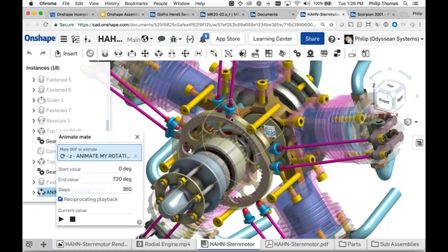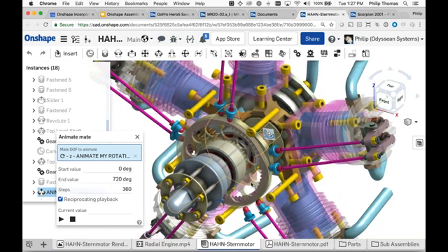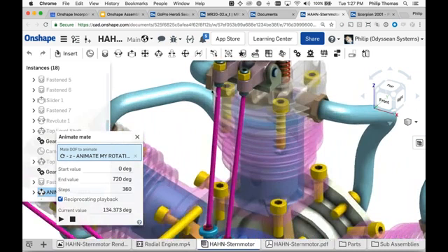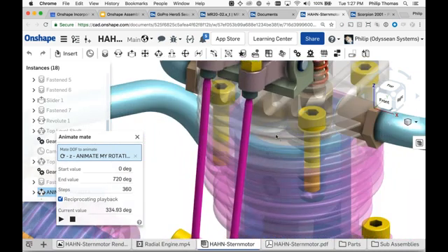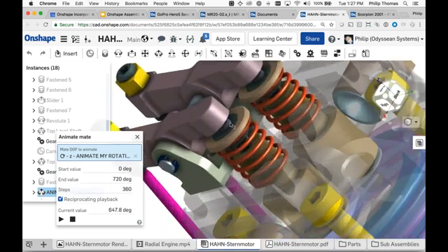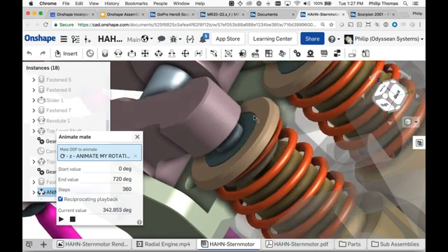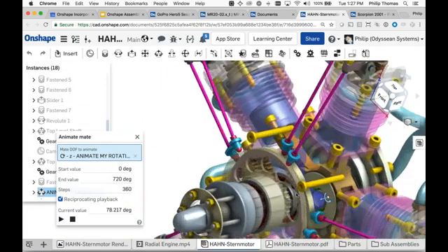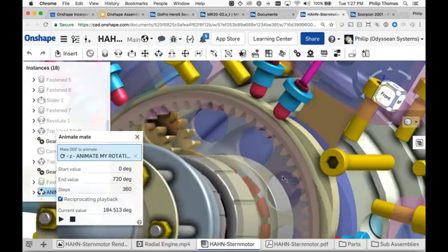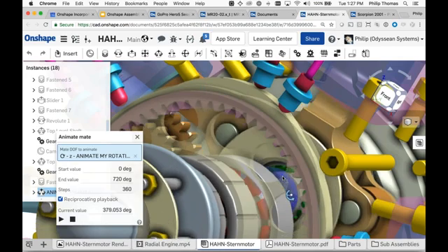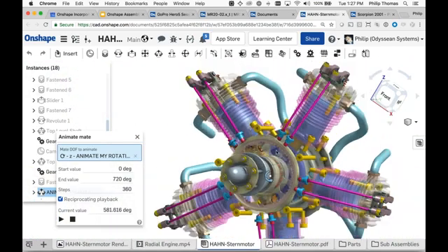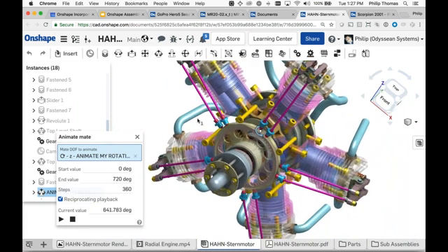There are actually a whole bunch of things that I found really difficult. There's an intake cam and an exhaust cam. There's a tangent mate between these cam followers. So there's two tangent mates here, 2 tangent mates here. So there's 10 tangent mates at this end. There are tangent mates between the ends of the push rods here, and there are tangent mates between the rocker arms and the top of the valve stem. So it's actually very complex, and that's before you add in the additional complexity of the ball bearings running at half the difference in speed between the inner and outer races. So I had a lot of fun doing this in Onshape, and it really did convince me that this was a better way to go.